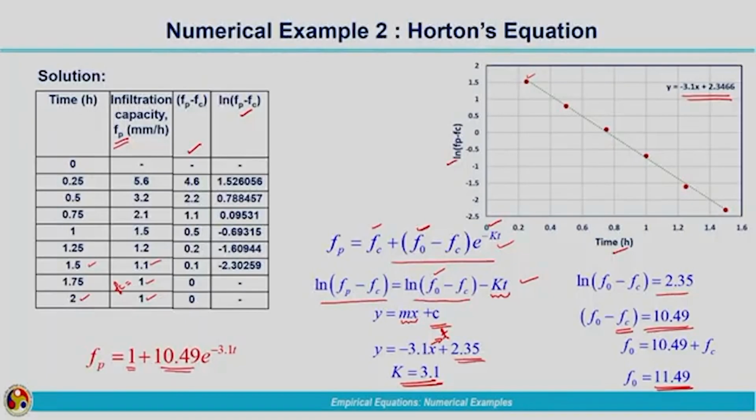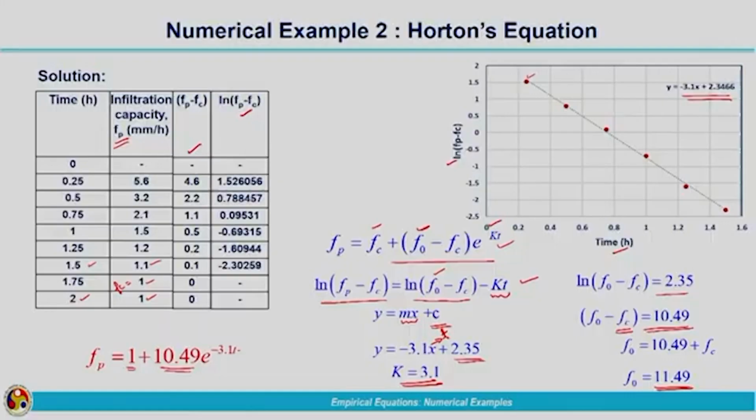Now you do not have to go for doing the experiment for this particular type of soil for different times. The t component is here in the exponent. So, from time 0 to certain time you can give the values and you can plot the infiltration rate, and also by integrating this equation corresponding to infiltration rate, you will get the cumulative infiltration also. So, for that particular soil, after conducting the infiltration experiments, we have fitted the Horton's equation. I hope it is clear to you how the Horton's parameters can be obtained from the given data.